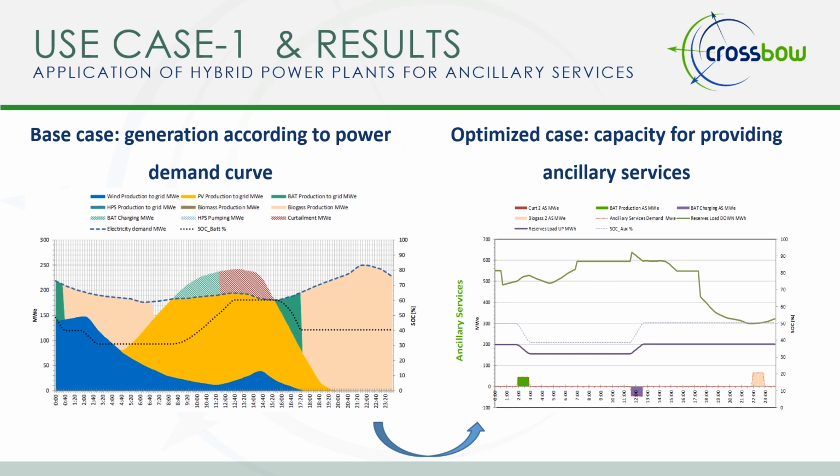Considering these limitations, the algorithm divides the existing battery into two subsystems: one battery model for load shifting operation and another which is used as a backup to provide ancillary services. This partition is realized by distributing the capacity of the battery in two parts. Finally, the battery initial state of charge shall be considered.